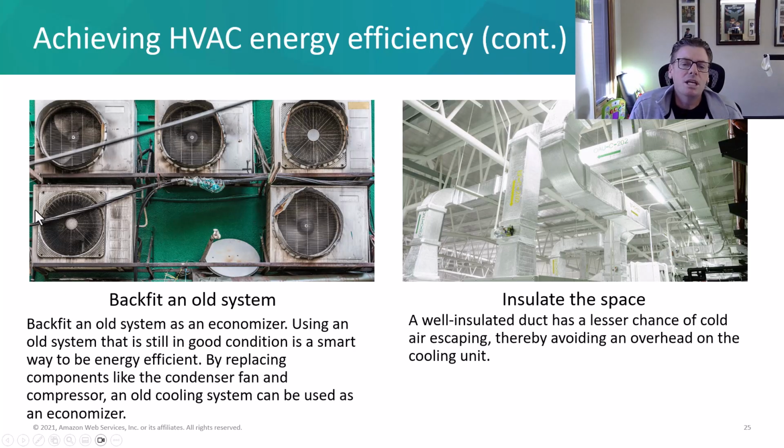All right, so one way we can improve efficiency is we can backfit or retrofit an old system. Okay, if it's still in good condition, we can replace some components with more energy efficient components like condenser fans or compressors, that kind of thing.